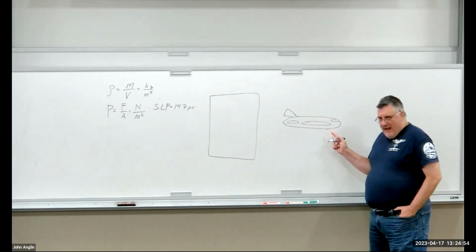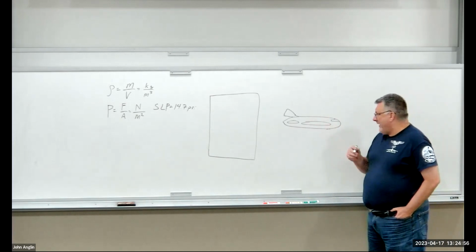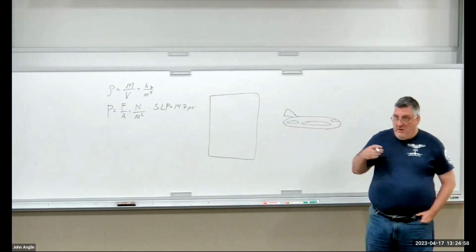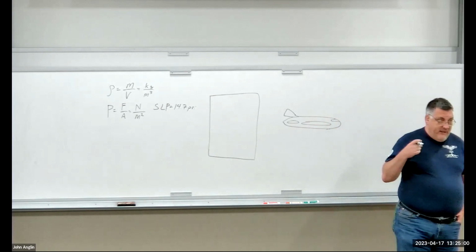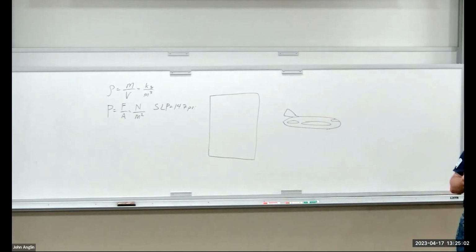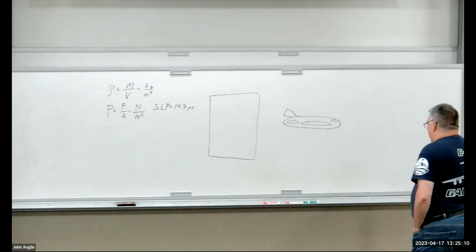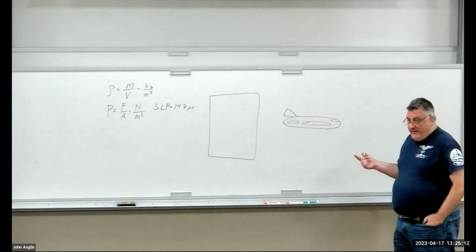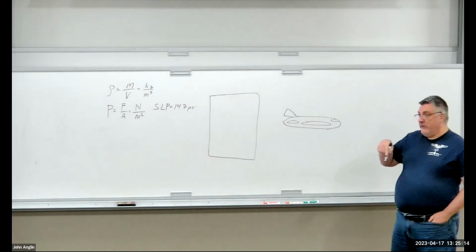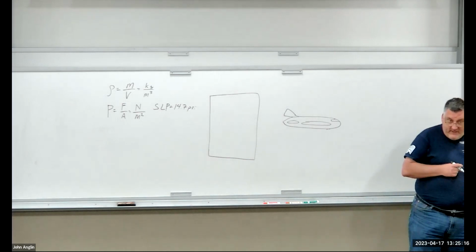So ultimately what happens is the inside of the aircraft might be at something like, typically about 10 or 12 psi. It's a little bit lower than actual sea level pressure. But outside the aircraft might be down to like 6. So that means we have what's called a differential pressure, PSID.